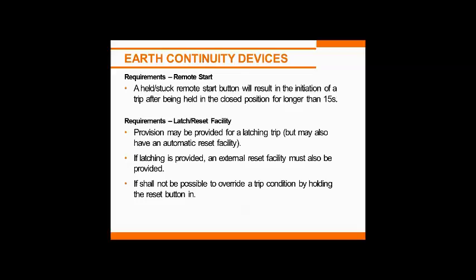Okay, and the final thing is an external reset, of course. If it's latched, you have to provide an external reset. And there should be no possibility of overriding any trip condition by holding the reset button in. And that's something we check fairly rigorously as well.